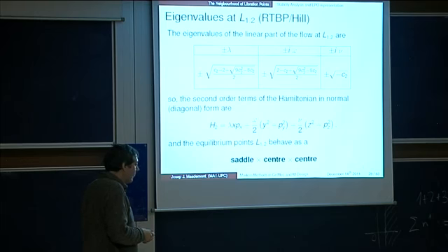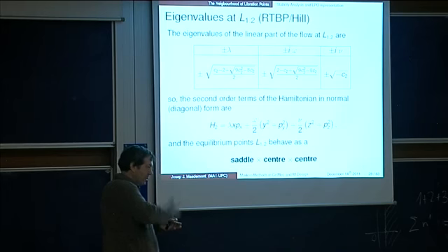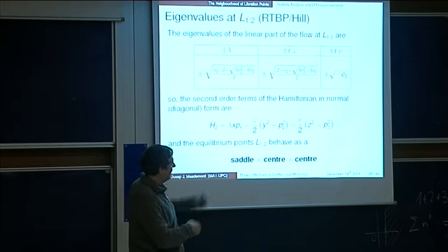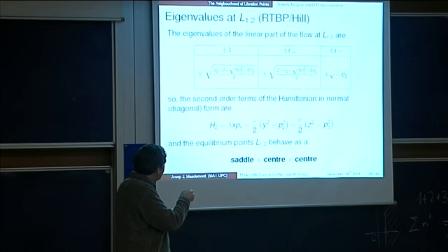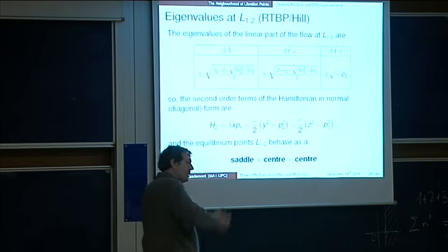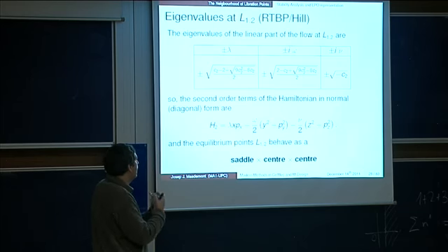So near the Libration points, we have essentially in-plane oscillations and out-of-plane oscillations that can be coupled. These are uncoupled, but they are coupled when you add higher order terms. But essentially we will have Lissajous orbits. But everything is multiplied by this saddle. So it's a center, in-plane oscillation, out-of-plane oscillation, times the saddle. And the saddle makes these orbits very unstable, and this will be related to the control of the satellites. So we will have orbits in the neighborhood of the Libration point, but they will be very unstable.